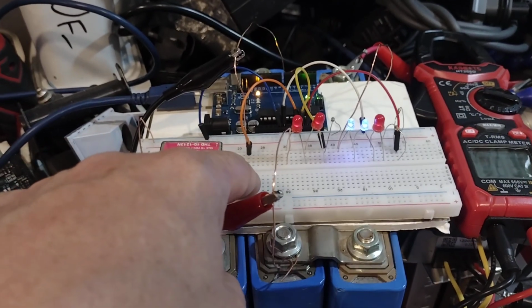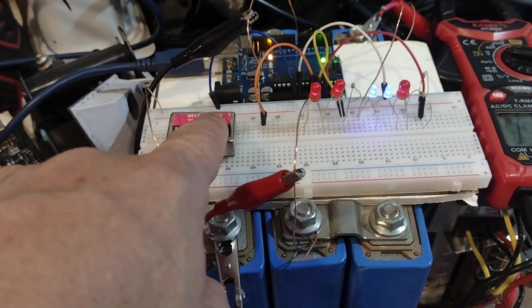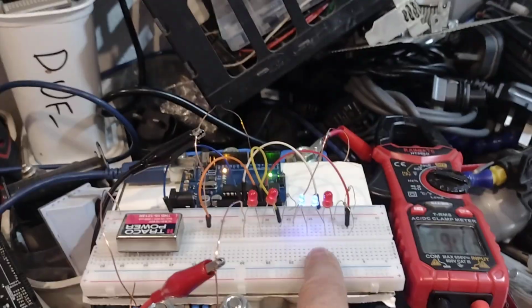This is the target voltage. It's still above that, because that's actually 3.9. So we can set that, and then I can connect that to one of the cells permanently, just for a test, to connect it to the end cell to see if the software actually does balance the voltage on that cell.